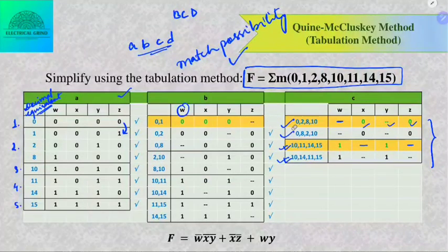Okay, so as we can see, there are two groups now, and both the groups formed have repeated cases. So we will see if there is a larger possibility of combinations. As we have seen, the possibility of combinations in 4 variables is 2, 4, 8 and 16. And if all 16 are combined, it yields a 0 literal, and if 8 are combined, it gives a 1 literal. If 4 are combined, it gives a 2 literal, and if 2 are combined it gives us 3 literals.